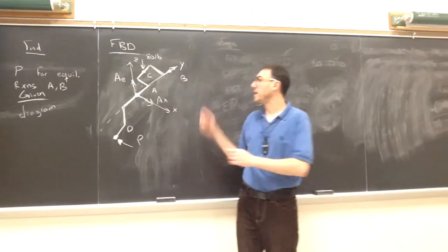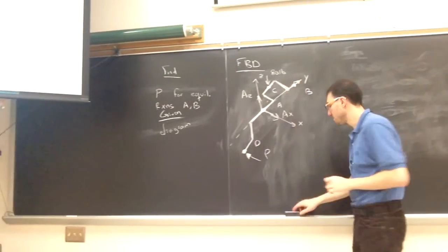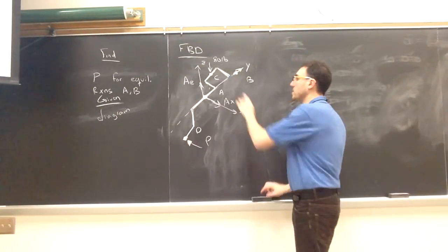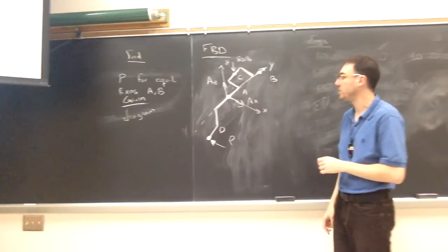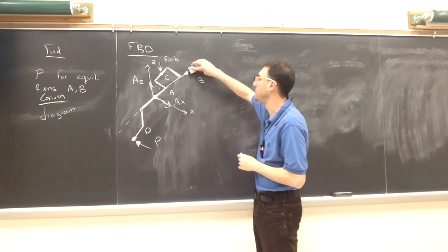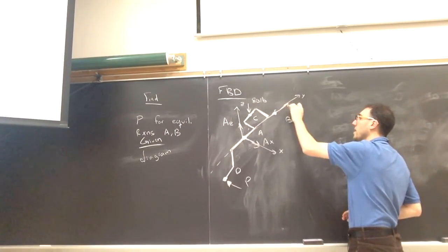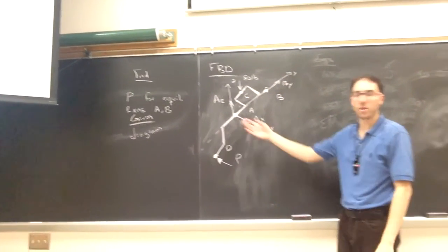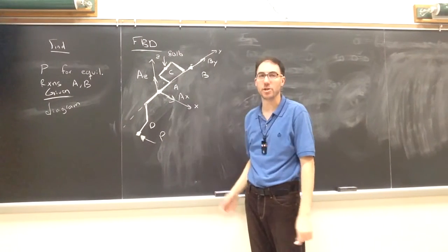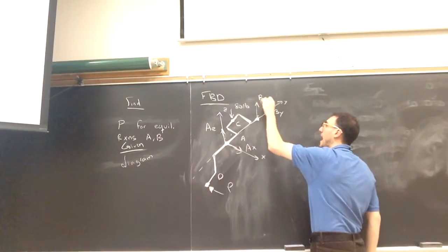Moving on to B, our other bearing. B is a thrust bearing. We just discussed the difference between the two. The thrust bearing prevents motion along the longitude of the shaft, so in this case, there will be a BY. And just like the journal bearing, it also prevents motion normal to the direction of the shaft. So we'll have a BZ and a BX.